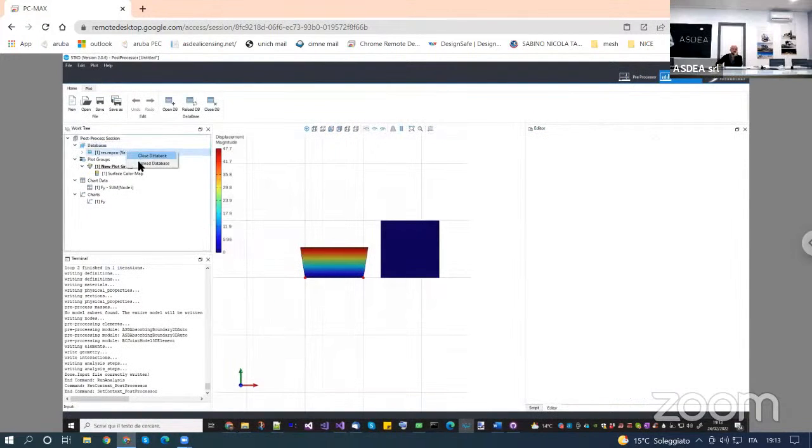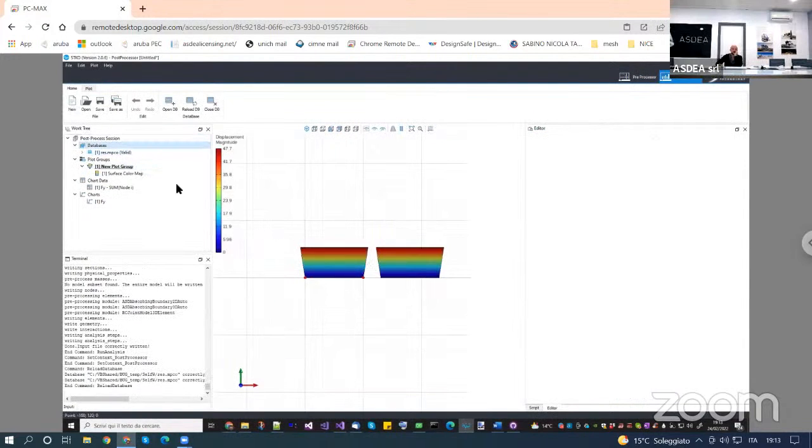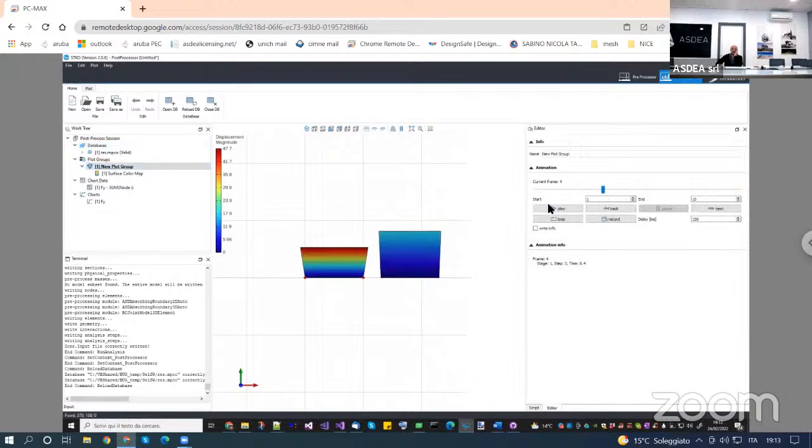And reload. Okay, now the output is the same, but if I do an animation, I will see that the second one is arriving at 100% of the load step by step. So this one is the main difference. As you can see, the output is the same because when you define the phase force or any distributed force in a continuum domain, STKO performs a nodal lumping in the same way it is computed inside OpenSees. So the output will be the same. The only difference is that the load is applied incrementally. That's all. Thank you.